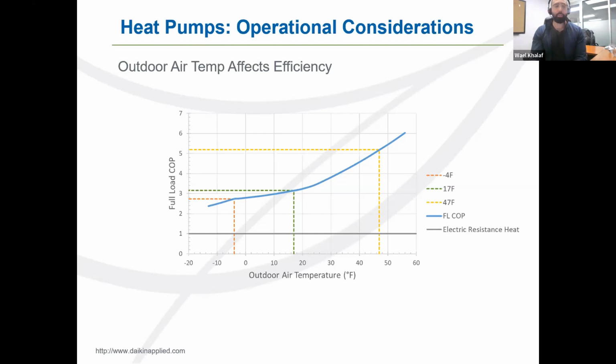So it's really important that we understand these factors whenever we're modeling a particular application, understanding how the ambient temperature is really going to affect our COP and ultimately the capacity that we're able to get out of our heat pump.